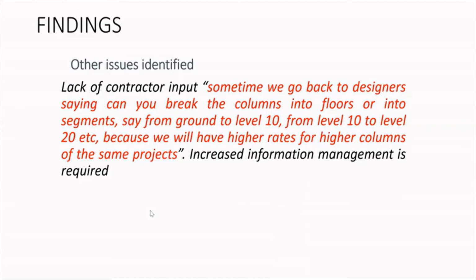So if the design team creates one large column, the contractor would have to break it up. That would be a problem for the cost estimator, because now he can't use the model to do his cost estimation. If he's been told to do cost estimation based on everything in the model, he cannot cost a 3 times 20, 60 meters long column for maybe 20 floors.